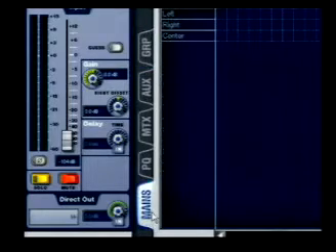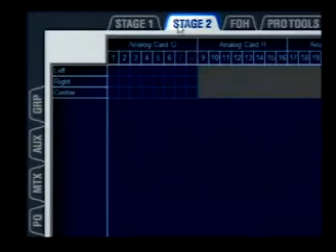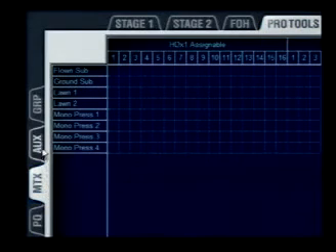We'll start at Mains. Notice our only choices here are left, right, and mono, or center if you are in LCR mode. You can choose to send these outputs out of any of the buses available, meaning hardware outputs on the stage racks, front of house racks, or FireWire and TDM record buses. You can then do the same for PQ, matrix, auxiliary, and group outputs.